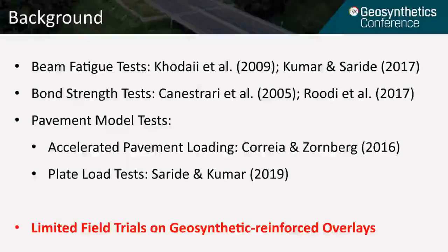Researchers worldwide have adopted various test methodologies to understand the influence of geosynthetics and the various mechanisms involved in retarding reflection cracks and enhancing the overlay performance. A few of the main evaluation methods include beam fatigue tests, bond strength tests, and pavement model tests.